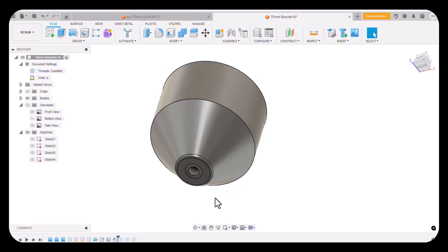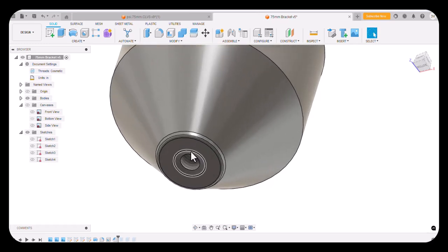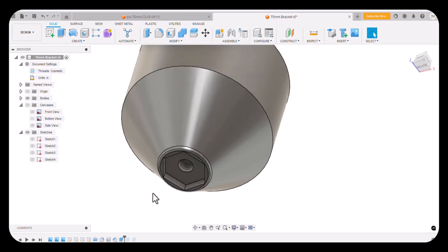All right, so now we're ready to go to the mill. Actually, maybe we can use the advantage of the hexagon also to hold this in place. So we put on our tooling, we have some kind of hex shape that this fits over, and then we put our screw through that, our fastener, to bolt this down tight. That keeps us from turning on the hex, and the fastener keeps it down tight against our tooling.